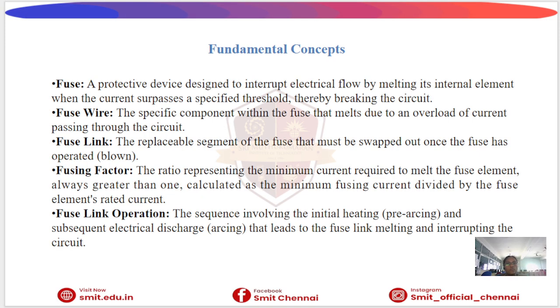Then fusing factor: the ratio of minimum fusing current to rated current. Fuse operation includes heating of the fuse element and arc formation before the circuit is interrupted. These concepts help us understand how fuse protection works.